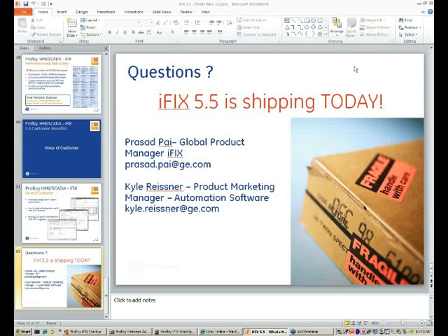Hey, Carrie? Yes, this is Steve Smith. Yes. Hey, something to clarify for those people that are doing the upgrades. There was a pathing change. They went from short install paths that existed in the old versions of iFIX to a different install path. So when upgrading older versions, if it was C Dynamics or C GE FANUC program files or whatever it was, the default install path for 5.5 is different on a clean install. So you need to take that into account whether or not you're upgrading and leaving your install path the same or doing a new install path.